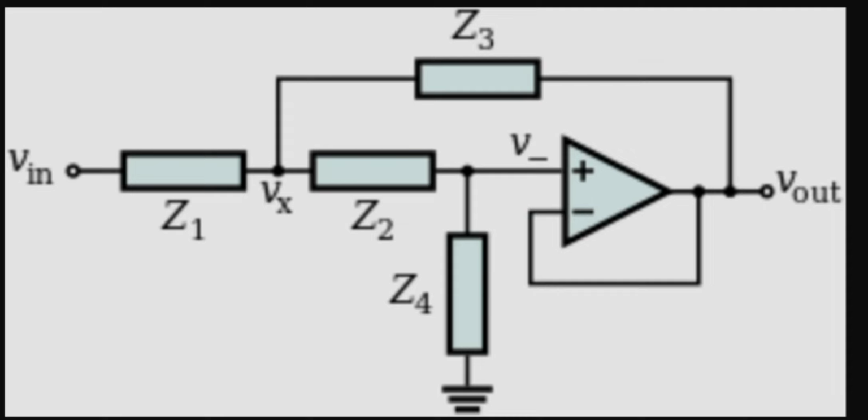That puts the amplifier to be used as a voltage follower or a buffer between output and input of the circuit. Since the gain A of the amplifier is practically very high, ideally infinite, we apply a concept of virtual short that makes the voltage at the negative pin equal to the voltage at the positive pin.